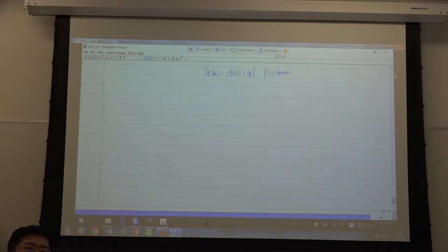So when you design a MEMS device, you should be very careful when parts are very close. They will touch each other. They will break. This is due to vacuum fluctuation of the electromagnetic fields, like a black body, like Johnson noise, just from this fluctuation dissipation theorem.